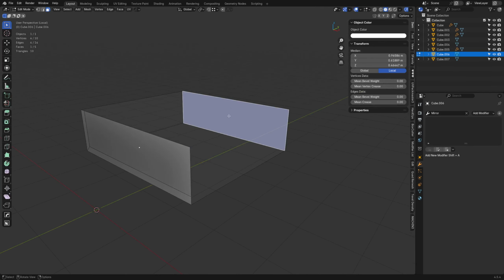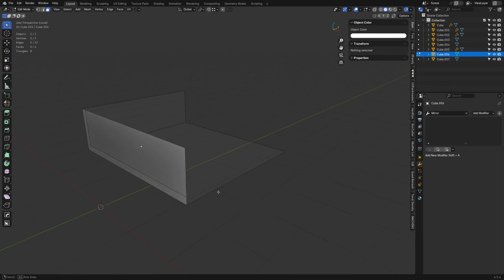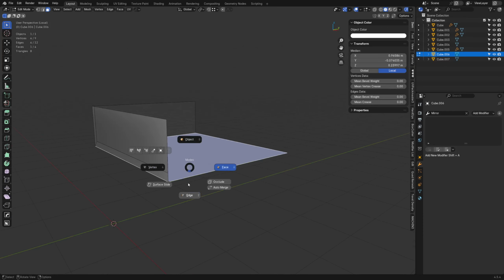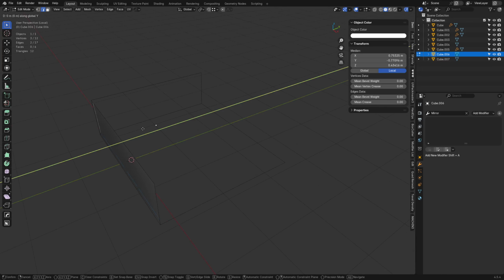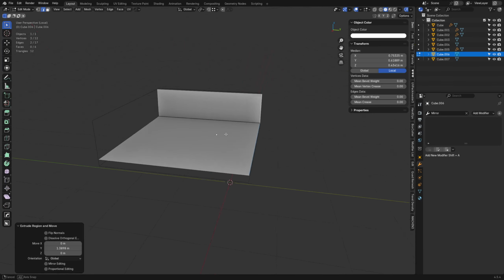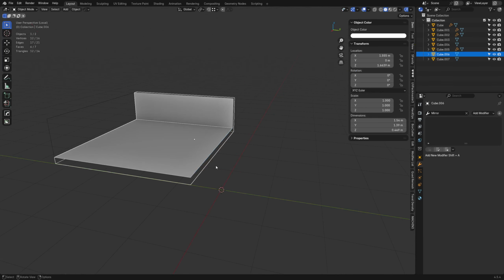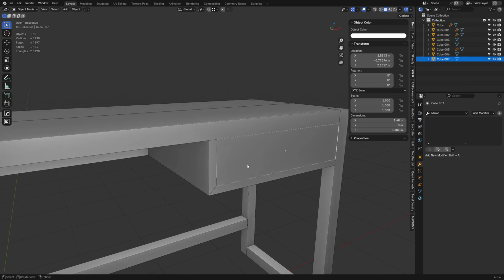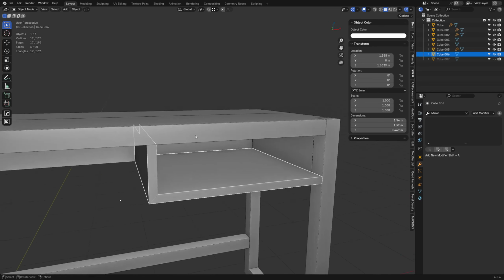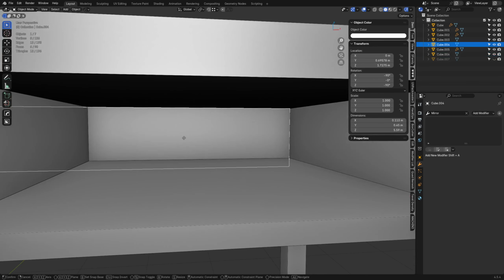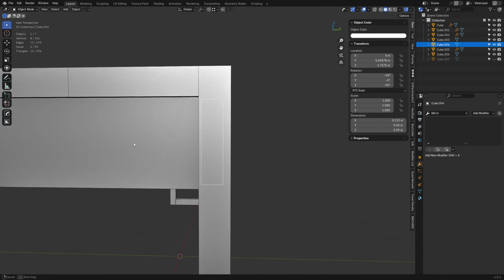The back face here, we don't really need. The bottom, we might. We do need like an interior space here. So what I'm going to do is press E, Y, and hold control and bring that in. Okay. Now, if we look at this without this, we don't want to see this for just a second. We can press H, going to hide it in the outliner, the eye icon, right? You can hide and unhide. We don't really need a backdrop in there because of this reason here, right? Like it's already got a piece of wood there.